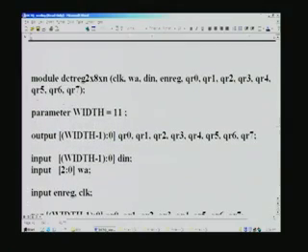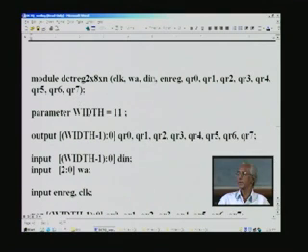So, this is the module declaration here, and it lists all QR0 through QR7 outputs, and these are all the inputs. Data in is what you have after the first adder, the 12-bit adder that we have seen, and that is the partial product that we need to store. At every clock a new data will be coming in DIN, which we will have to route to one of these registers.